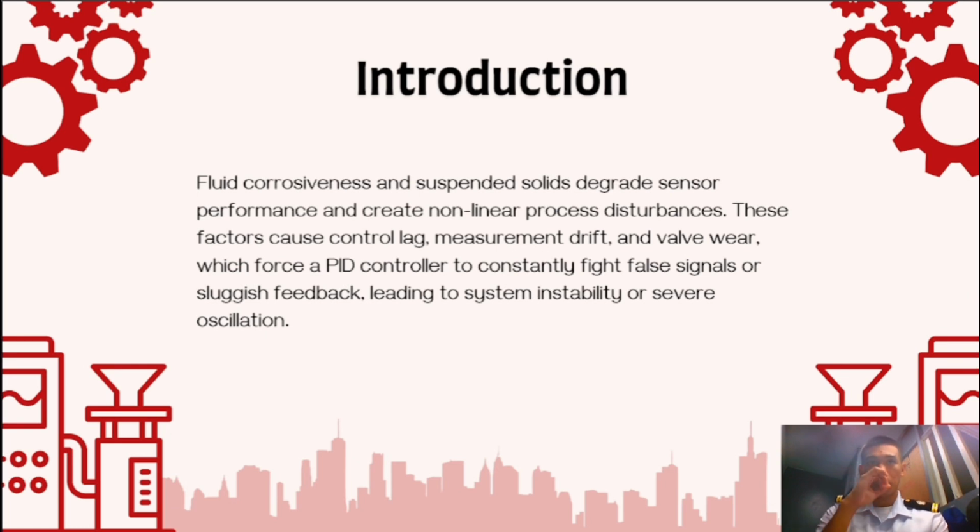Introduction. Fluid corrosiveness and suspended solids degrade sensors' performance and create nonlinear process disturbance. These factors cause control lag, measurement drift, and valve wear, which force a PID controller to constantly fight pulsed or sluggish feedback signals, leading to system instability or severe oscillation.